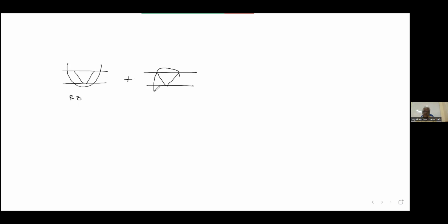If you are bending like this, face bend. Why am I putting a plus here? It is always one root plus one face, or two root plus two face. They will come together. Side bend will be, suppose this is the same, if you are bending like this, it is called a side bend.